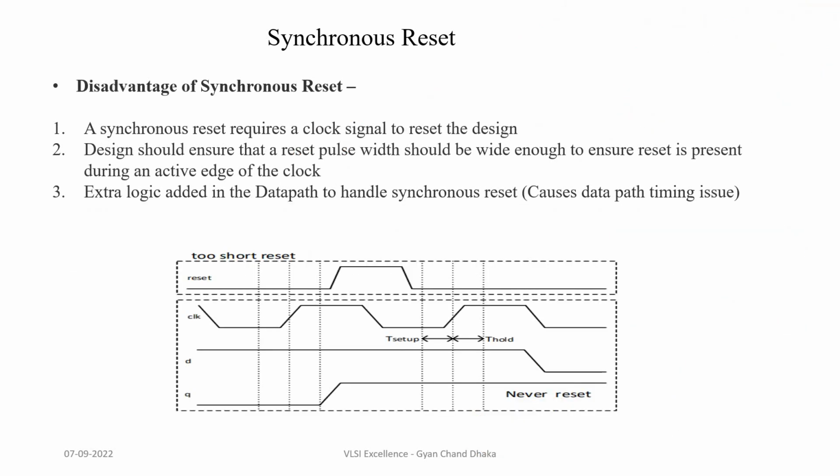Now let's see some of the disadvantages of synchronous reset. The first disadvantage is that synchronous reset requires a clock signal to reset the design. Just remember that the application of reset is to put our design into a known state, right?